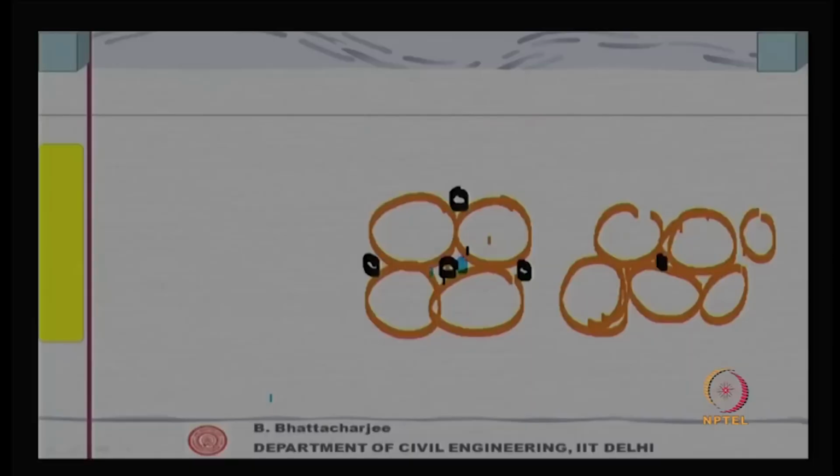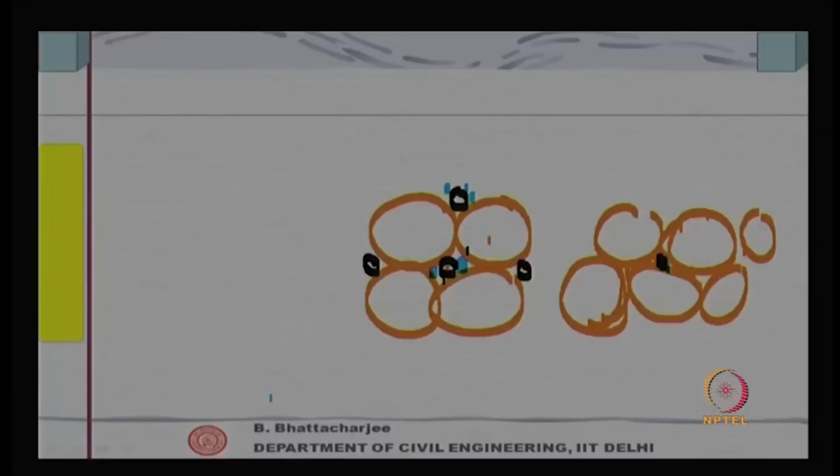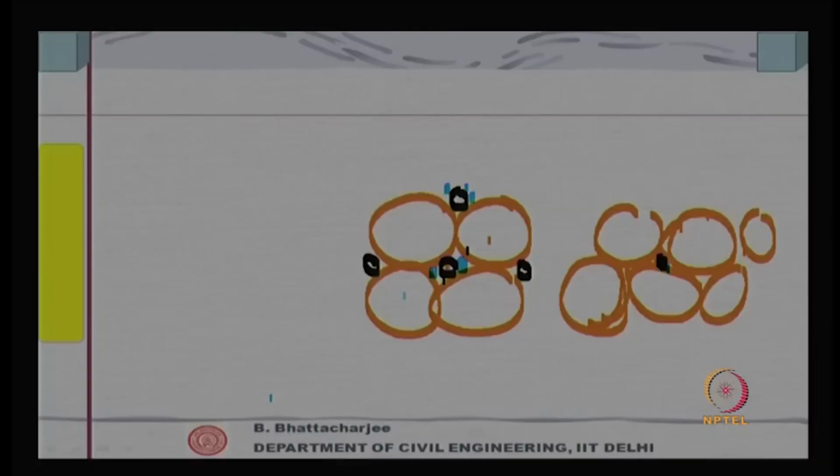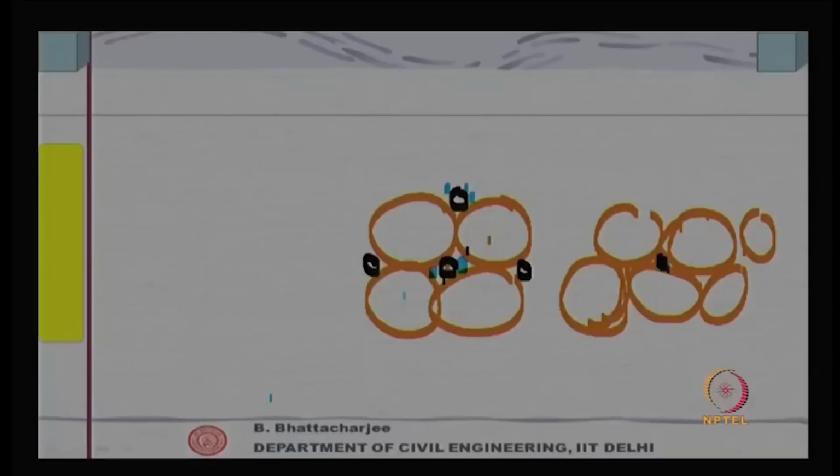And if you want to reduce this void further, then you use maybe a third finer particle. So, if you put finer particle, they will go into the interstices of this particle itself and reduce the void. So, therefore, void contents depend upon packing characteristics, shape of course, is also a function, but for given shape, given type of packing, number of particles or size distribution of the particle governs the packing characteristics.